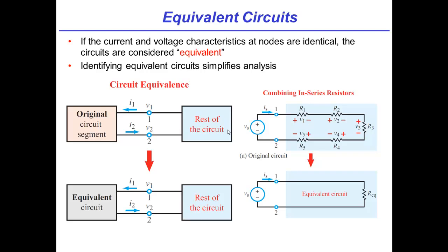All right, so the reason we care about this is, let's say I have a huge circuit that has hundreds of resistors and multiple voltage sources, etc. I can build a box around some fraction of it. I can do all those analysis KVL, KCL tricks that I've been teaching you and simplify the circuit to something really simple. I might be able to replace it by just one resistor or one resistor and one voltage source or something like that. Then I can draw another box and simplify that, and I can essentially break circuits into smaller, more manageable chunks and analyze them separately and then simplify.